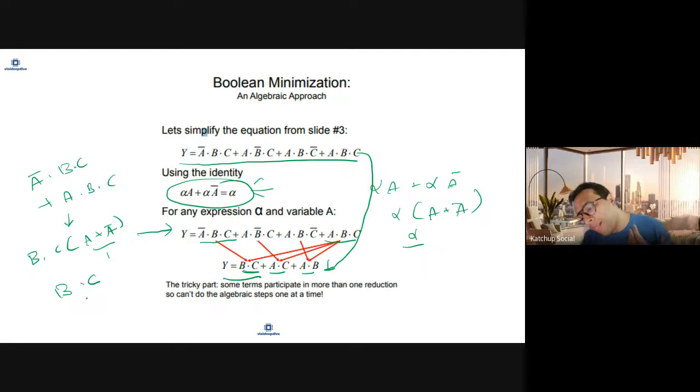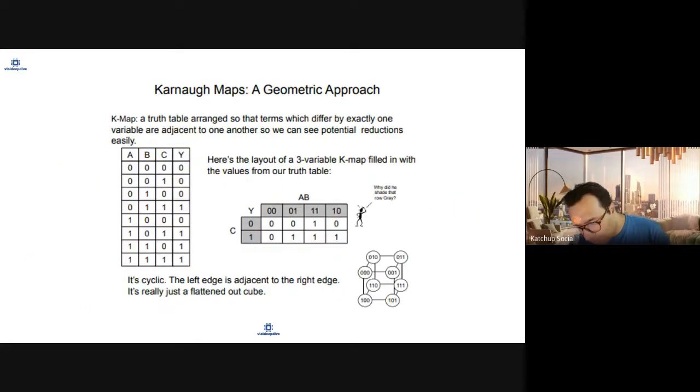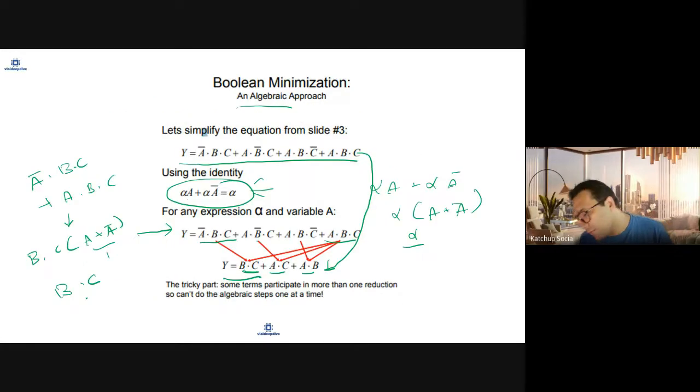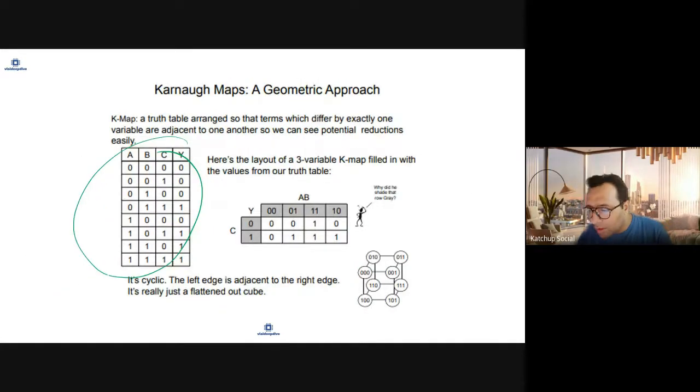And this helps reduce the amount of logic and in turn the amount of area. So this Boolean minimization, either through an algebraic approach or through using a Karnaugh map, whichever method the synthesis tool uses, there are multiple algorithms which exist. It will reduce the Boolean equation which is created. So what is happening is you give your HDL hardware description, it will convert that into Boolean equations.